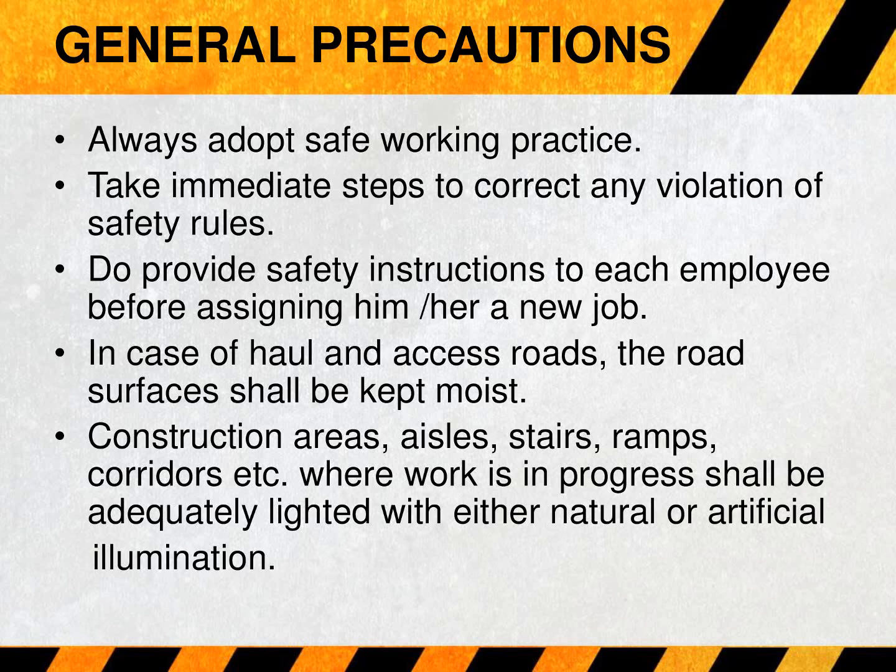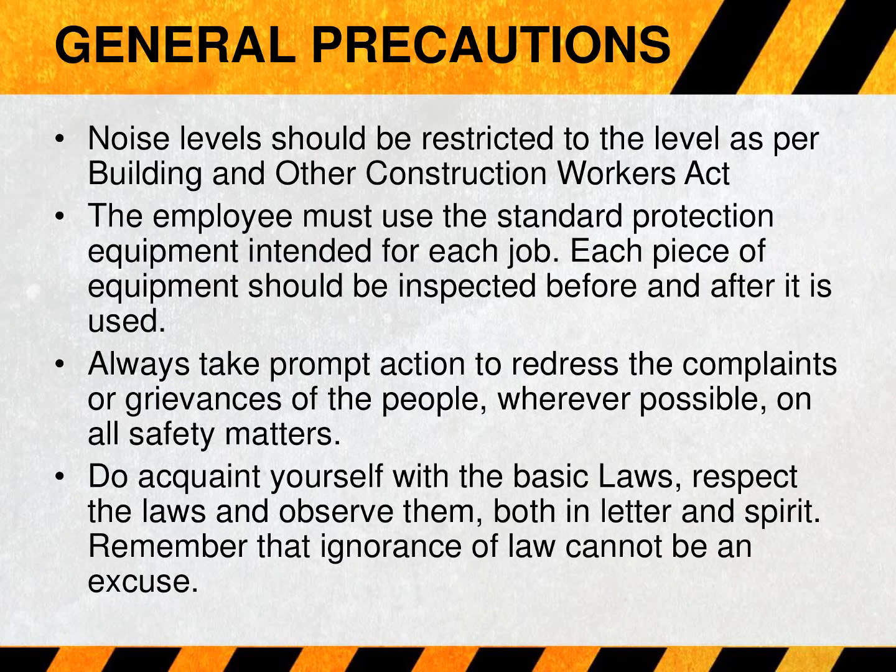In case of haul and access roads, the road surfaces shall be kept moist. Construction areas, aisles, stairs, ramps, corridors, etc., where work is in progress, shall be adequately lighted with either natural or artificial illumination. Noise levels should be restricted to the level as per Building and Other Construction Workers Act.